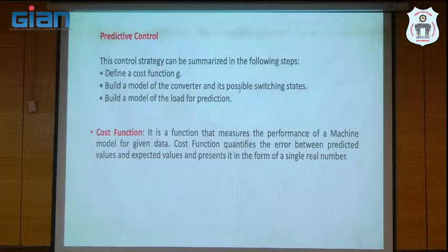In model predictive control also, in the cost function, please start to understand: the model predictive controller is a multi-input and multi-output system. By taking a single equation, we can calculate the required voltage. By the iterating process, we can identify the optimal voltage vector required for the next sample period.